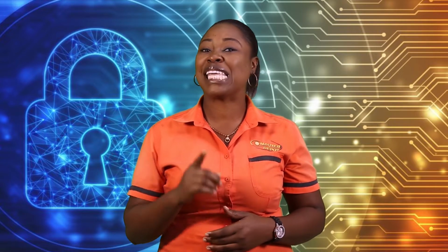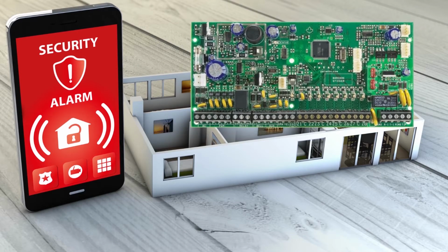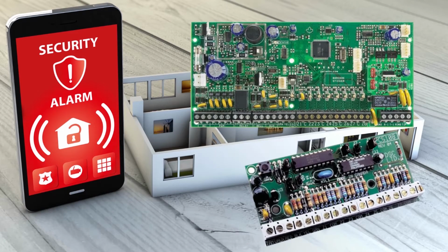Knowing the number of zones that will be monitored is key in deciding what size panel and how many zone expanders to add to the basic board. For example, an 8-zone alarm system will need an 8-zone expander to make the system a 16-zone alarm system.